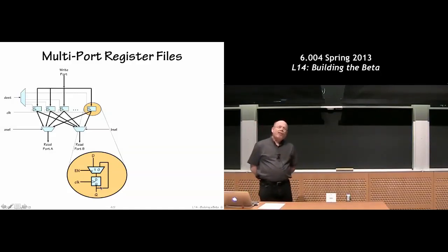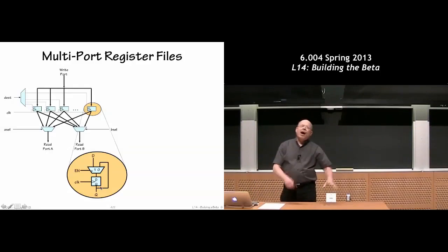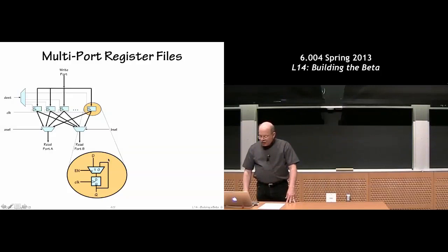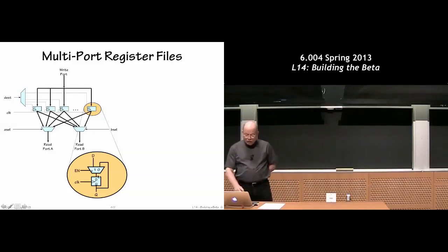So you can say, well, why don't we just do something fancy with a clock, do some logic so that the rising clock edge doesn't happen. That turns out to be fraught with danger as you get down to low-level circuit design. This little diagram here, which involves this little 1-bit multiplexer, is a much safer way of implementing clock-enabled registers, and almost all designs that I know of do that.